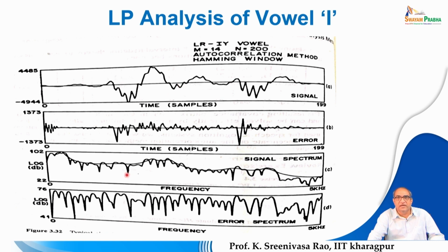And now we separated that, right; in the analysis phase we got the error signal. So, if you compute the error spectrum, you can see this is the spectrum, whereas in the LP analysis, we got the linear prediction coefficients. With that, if you see the synthesis filter, which is nothing but an all-pole filter, and plot its spectrum, you can see this smooth spectral envelope, right.